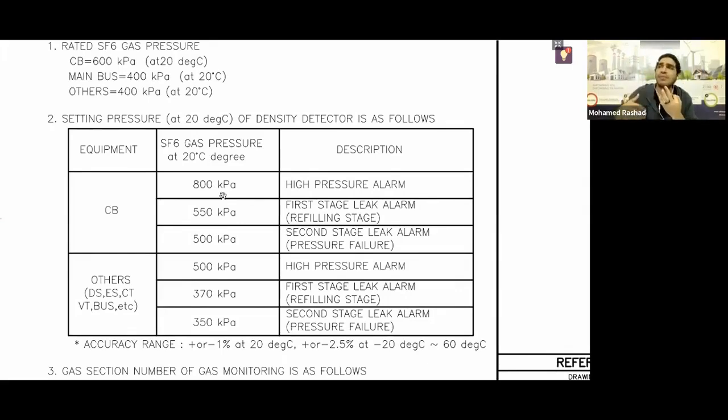One is for when you have high pressure, so this limit switch closes, and 2 are for when the gas pressure drops to the first level or the second level. So low pressure 1 and low pressure 2. All right, so when the pressure increases, a limit switch closes. And when the pressure drops to the first level, a limit switch closes. And at the second level, another limit switch closes. How many is that? Very good.